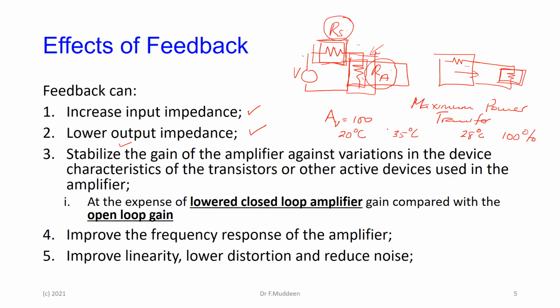Inside the AC, the lab, the humidity is probably 10%. It's very dry. So you design it in the electronics 2 lab upstairs. You come out on a day like today where the temperature is 8 degrees hotter, but the humidity has gone from 10% to 100%. You want the amplifier to still be giving you a gain of 100, maybe plus or minus 5.